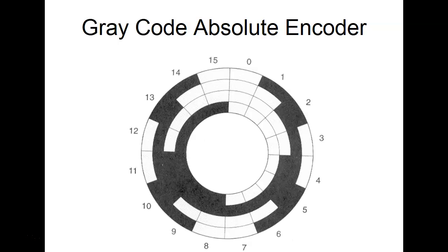So this is a Gray code encoder. So notice it doesn't go 1, 2. So 2, if I did that in binary, we'd actually say it was a 3, but it's a Gray code encoder. So all these are not going to be the same, but you need to have the basic difference of a Gray code. So Gray code is a what? It's a high-speed counting code where only 1 digit changes between counts.